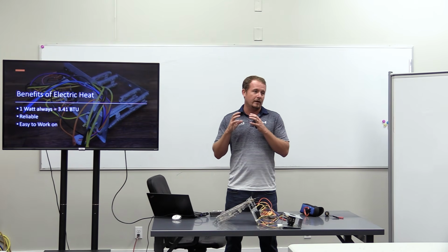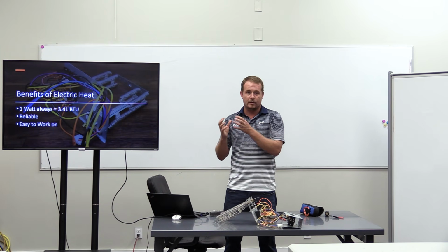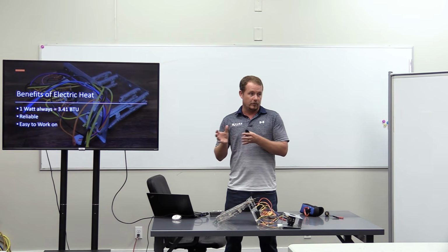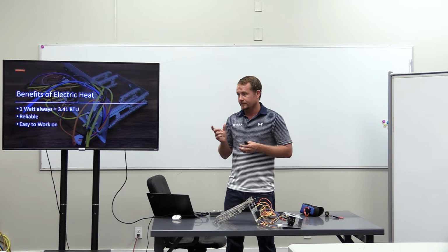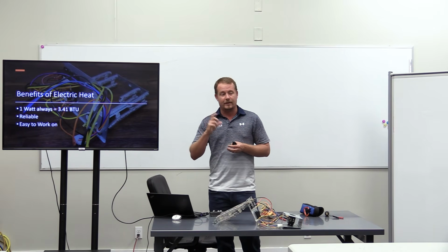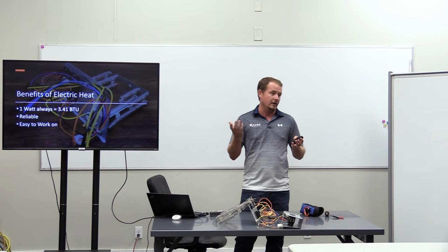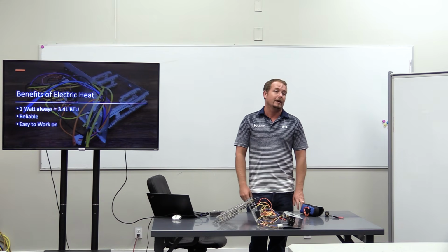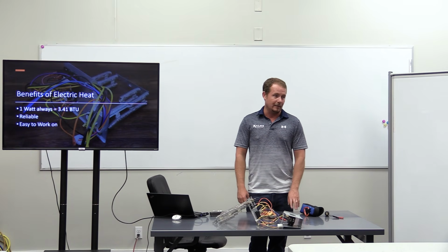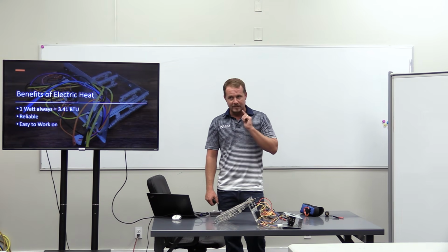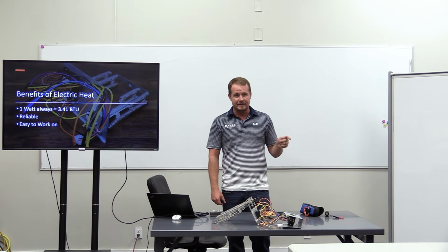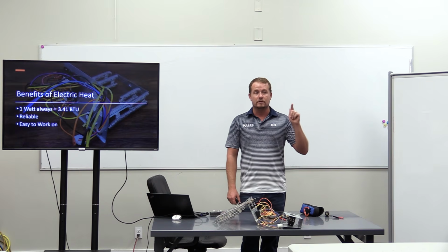So like, what gives? Well, as it turns out, when they had originally wired up the smoke alarms, they were supposed to break red in order to shut the unit off when the smoke alarms went off. Well, they didn't. They broke orange. And so when you break orange, you have no 24-volt call on your reversing valve, and it just locked the thing in heat mode. And so I didn't test it the way I was supposed to. So a couple mistakes there. One is, whenever you're going to check electric heat, especially if you don't know the last time it's been tested, you need to talk to the occupants.